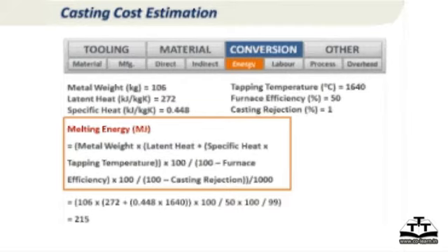But here you can actually estimate the cost a little more accurately, and it does make sense. If the pouring temperature is a little higher, or the holding time is longer, you can incorporate holding time in this, and you can say I have additional energy cost because of that. Now one trick we have used and we recommend to foundries is, what about other energy costs? Cost in mold making and core making and fettling and so on. Okay. Now you can't go around estimating every cost, that's too painful.